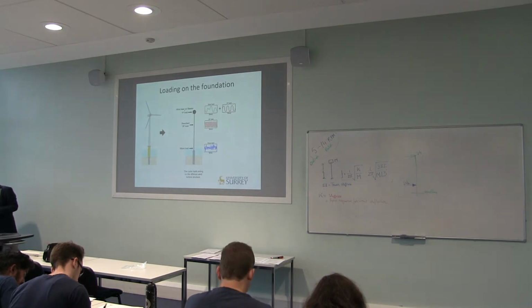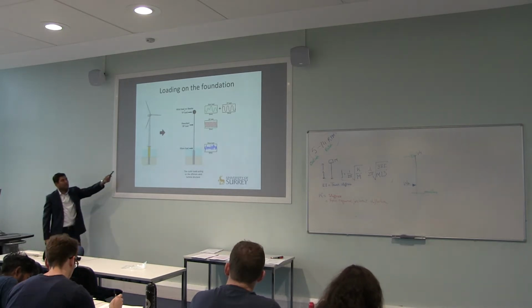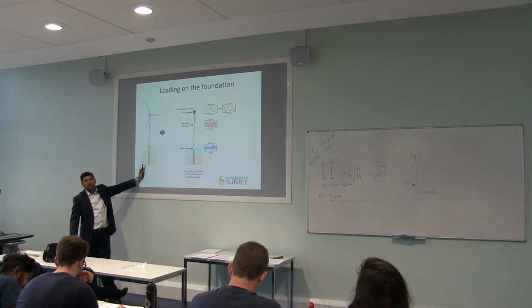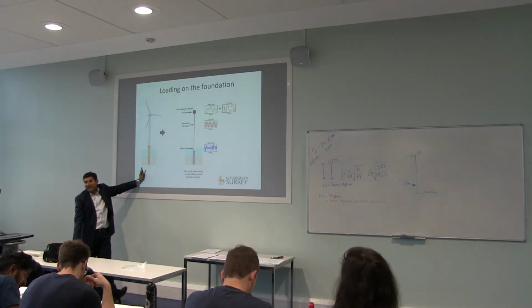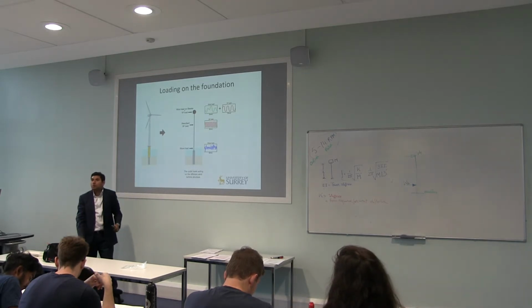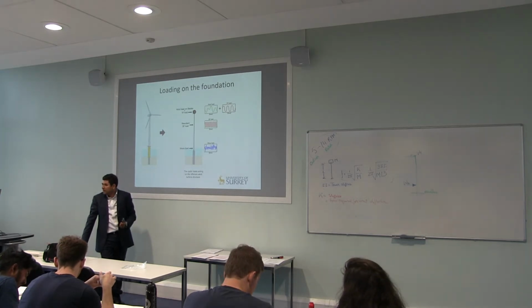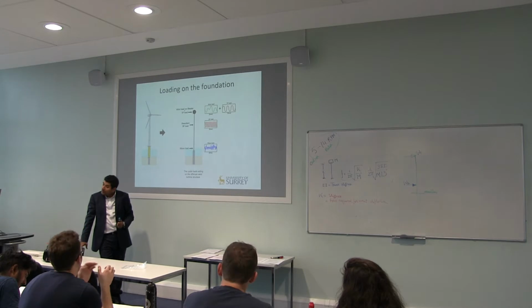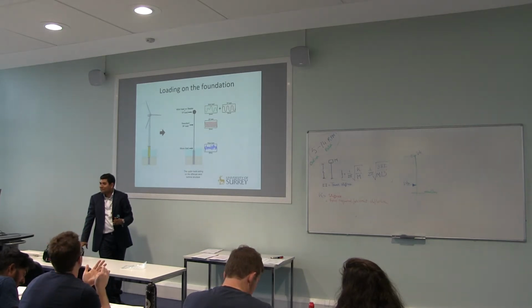Now, another interesting thing is, this structure has a frequency of 0.22 Hertz for an 8 megawatt turbine. For 8 megawatt, I will show it in more detail, 0.22 Hertz. For 3 megawatt, 0.34 Hertz. Typical wave frequencies can be quite close.